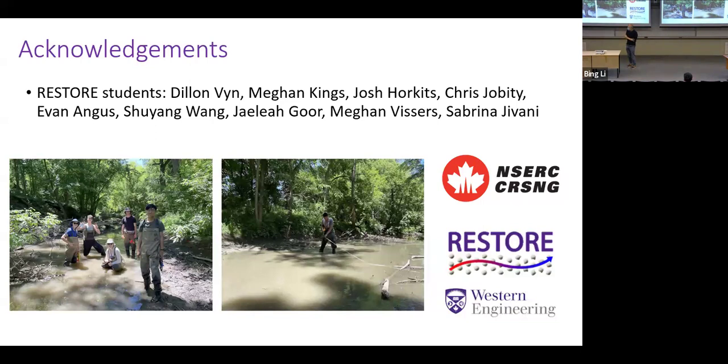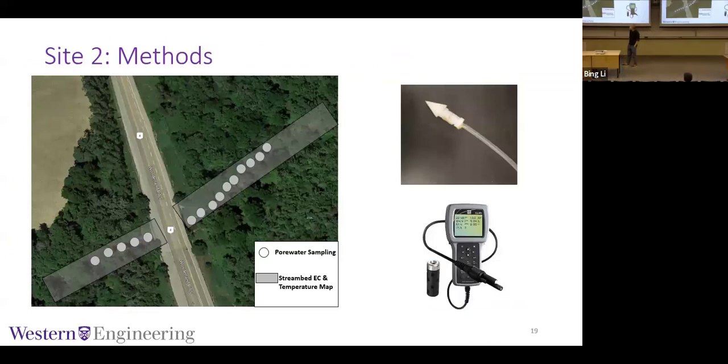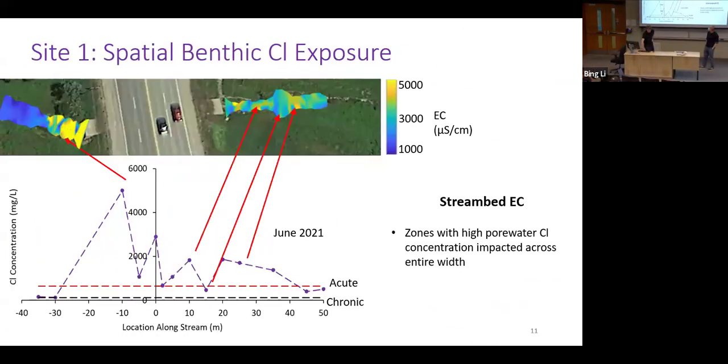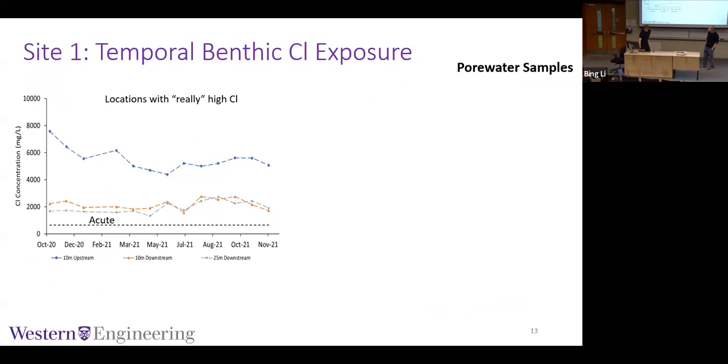I have two. The first is, are these very high chlorides consistent, for example, just when they're discharging after a snowfall or something, or is it relatively stable? Yes, there are really high peaks in chloride content. This one here is minus 10, so it's this line here. There are fluctuations, but it's pretty stable. Within the summer, it's still around 5,000 milligrams per liter. So it's not just during the salt or the winter season.